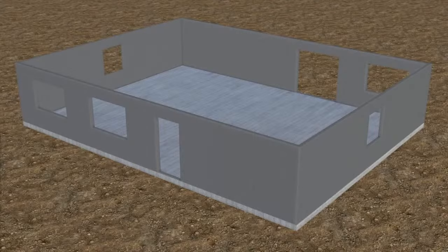Traditional builds, however, are very good in terms of thermal mass, which is the building's capacity to store heat. This means it takes this type of building longer to respond to changes in the heating or cooling conditions. If the structure is heated to a constant temperature continuously, this can be of benefit to its energy efficiency, but if not, it can mean the building takes much longer to warm up or cool down.